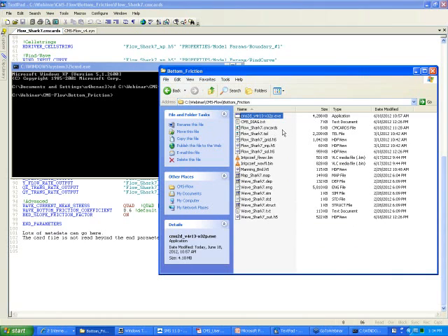Having the executable within the same folder is good because even though the executable has the version and revision number in its name, if you give that project call to somebody else and it's maybe an old project, they may not be able to find that executable if they want to rerun the model. Okay? So it's always good to save the executable in the same folder where you're running your files.